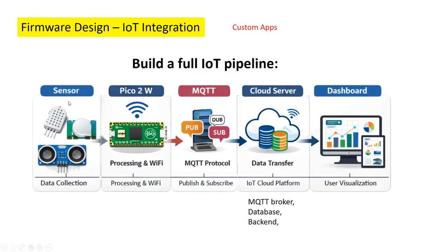First, we have our sensors connected to our Pico-W, and then from our Pico-W, we connect to our Wi-Fi and set up our IoT protocol for communication. That is for transmitting our data to the cloud server. And in this case, we'll be using MQTT, which focuses on publish, subscribe, and a broker setup. So I'm going to show you how to use that publish and subscribe model.